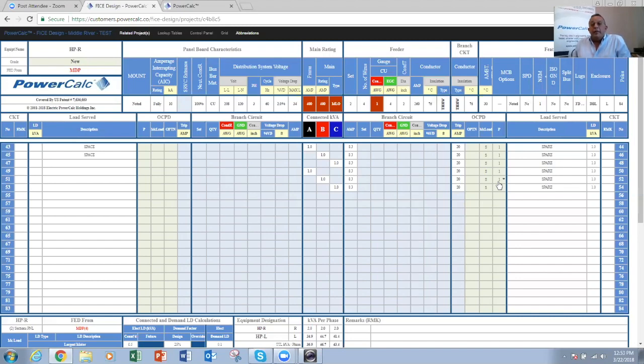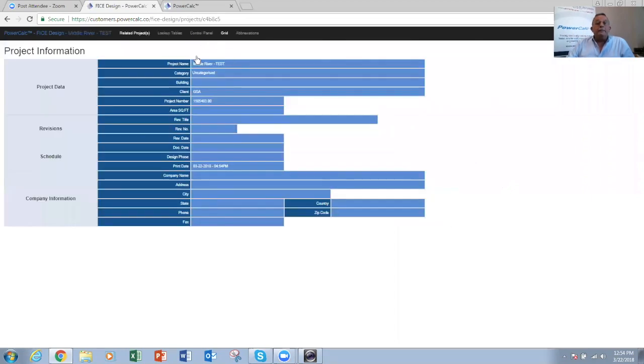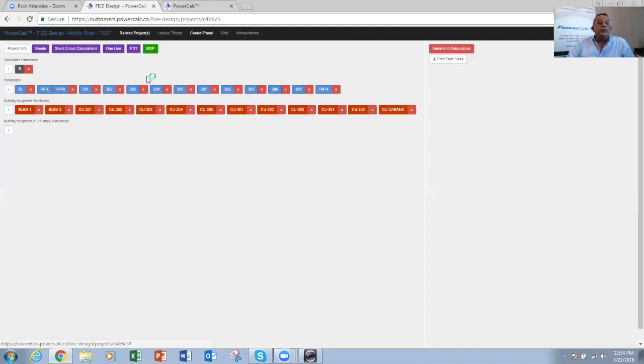If I have a circuit breaker that's stamped 10,000 amp on it, that means it can sustain up to 10,000 amp going through it without any physical destruction or starting a fire. So it would be intact for that particular value of fault going through it. Same thing for the short circuit rating of the panel. It's rated based on fully rated.